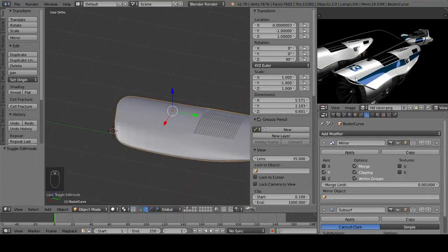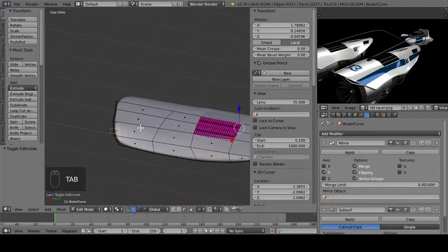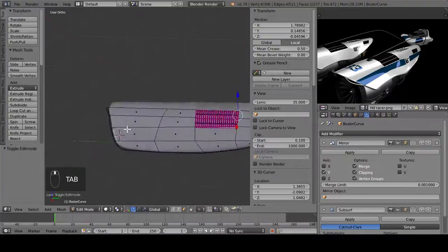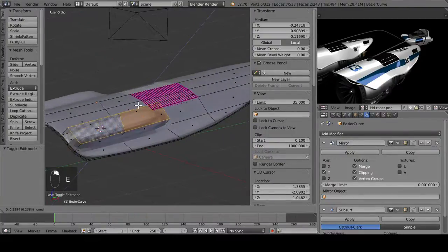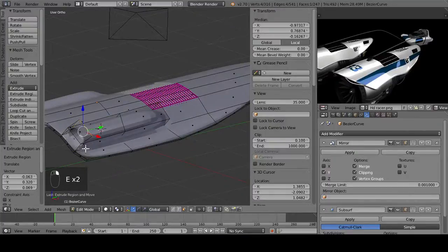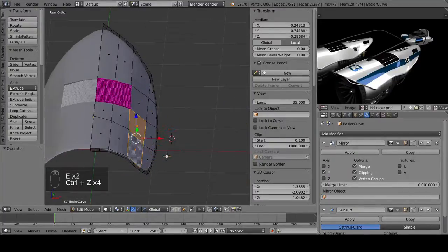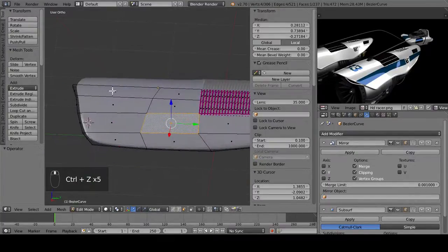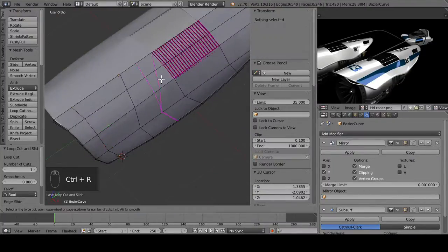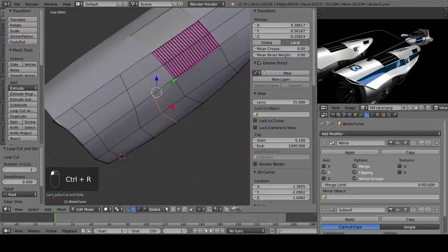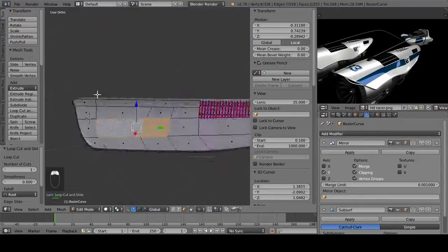Now another bit I want to show you is something I didn't put here because I didn't really care for it, but how to make scoops come out of the top, because it's a very cool effect, although I don't really care for it. So we want to extrude it up and add in vents sort of like this, but I feel like that's just a bit too close to the front. So I'm going to add in a loop cut, give ourselves some more geometry to work with. I think I'll add another one back here and just use this bit here.